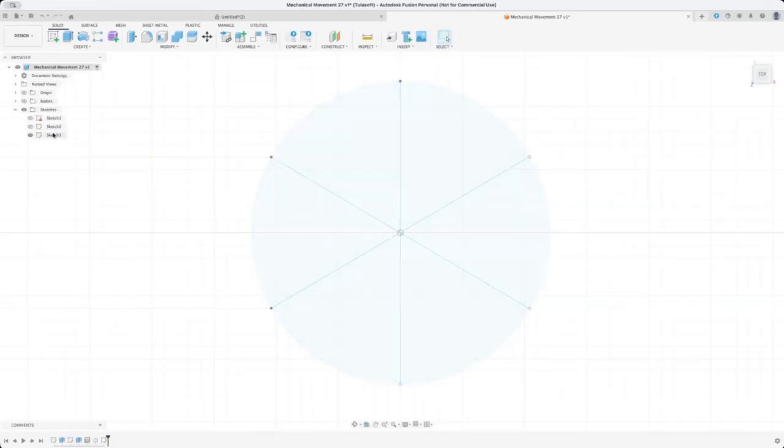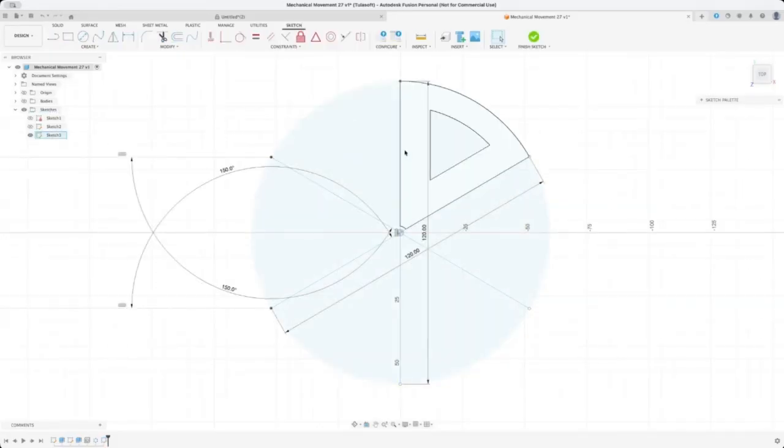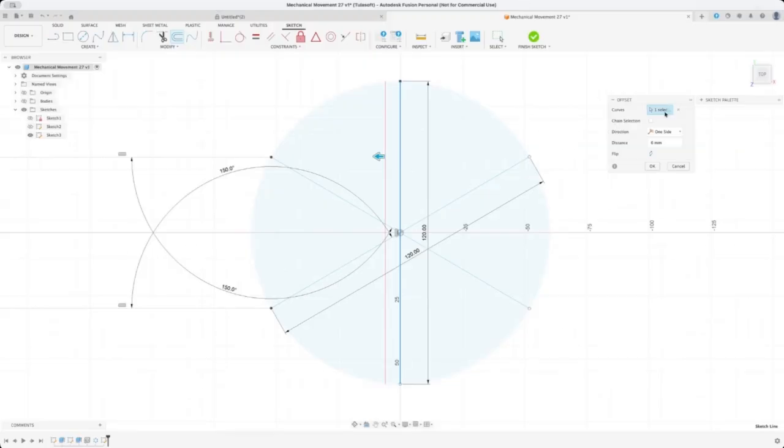With the groove guides in place, we can then use the offset tool to mark the sections which we will cut out from our flywheel. This time, we use the asymmetric option so that the offset applies on both sides of the guideline. When we have done this for all the sections, we can then proceed to select the relevant sections for removal.